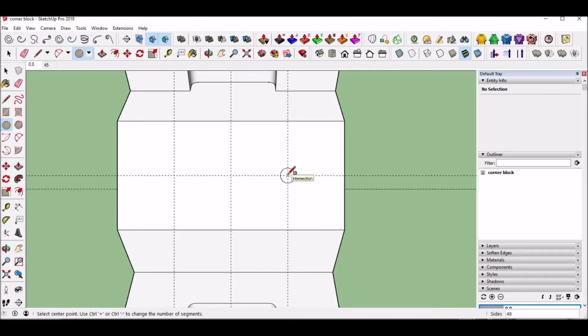So let's talk about the first second. Actually, let's go back to E and then C for circle. I'm going to type in 12. Okay. See how you can see the 12 sides. It's really funky. Whenever you draw a circle, doesn't matter how many sides, always draw it along an axis like this, so that these points are along the guides, so that they're not off like this. You don't want them like that. You always want points on them. So let's go with 48 sides.